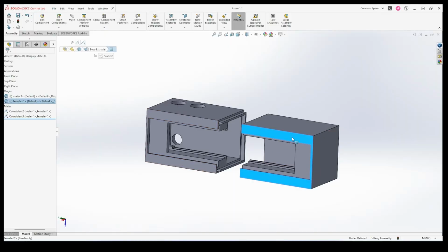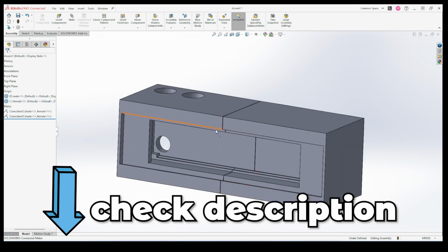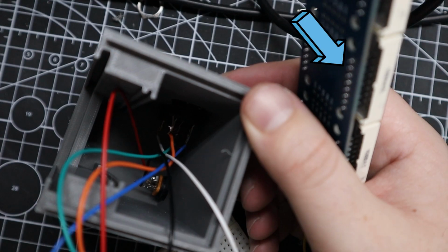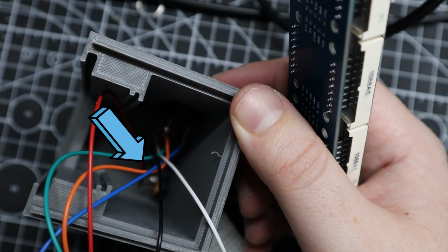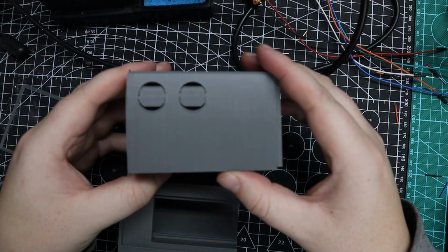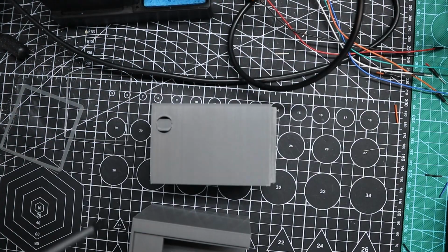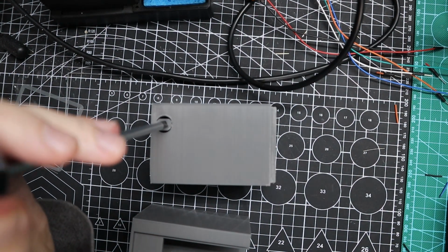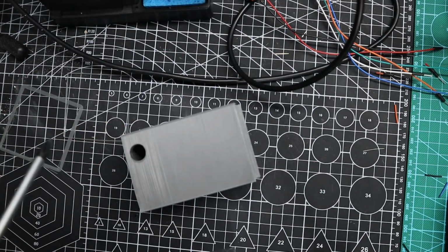The 3D printed case I designed in SolidWorks. I will include the 3D models if there is any changes you want to make with it in your favorite software. The module slides into the grooves, and there is enough space here inside to push in the whole breadboard with all the wires. I added 2 holes for the push buttons and a DC socket. In the future I will make a simple PCB to keep everything neat, and also maybe add a battery with a charger, but for now this will do.